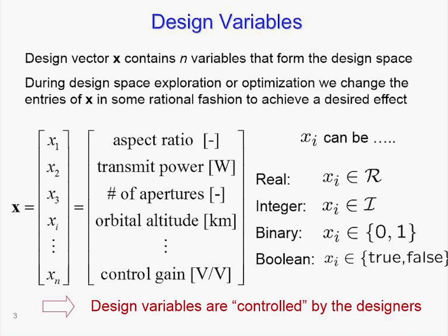So we'll have M1 inequality constraints, and the constraint is written that Gj for the jth constraint has to be less than or equal to 0. So this might be a constraint that's something like stall speed. You need a constraint on stall speed, and you don't require the speed to be anything in particular, but you've got to make sure that you stay above the constraint. And you would bring everything over to the left-hand side and make the constraint less than or equal to 0.